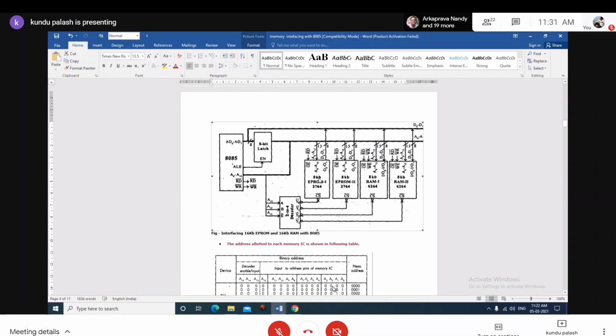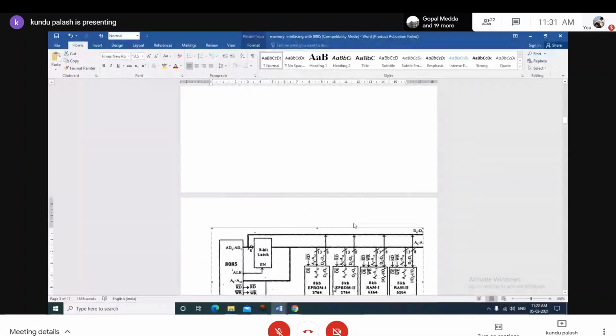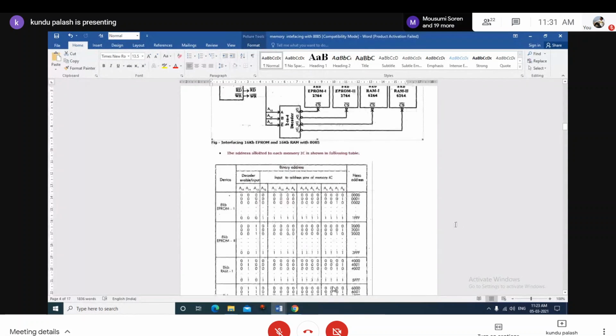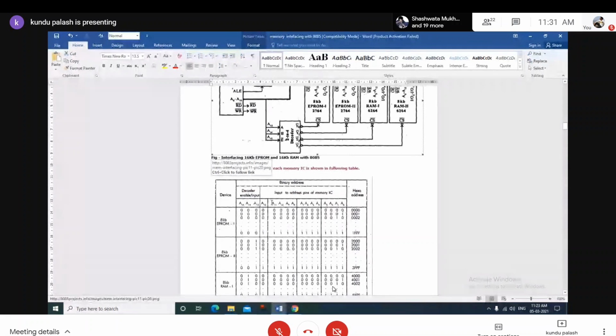You calculate. Similarly, for another equal size block, 13 address lines will be required to select any one of the unique address locations inside block 2, that is EEPROM 2. So this will select the partition. This will select the decoder output, which partition. And within the partition, the rest of the address lines will be utilized to point physically to the memory address location. So what will be the absolute address location after decoding? You can see the rest of the address lines, from A0 to A12, which can change from all 0 value to all 1 value in the respective row.